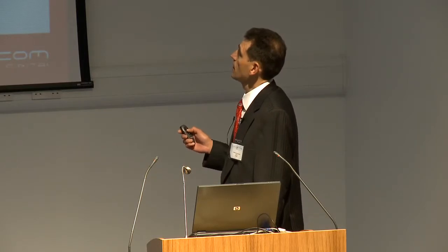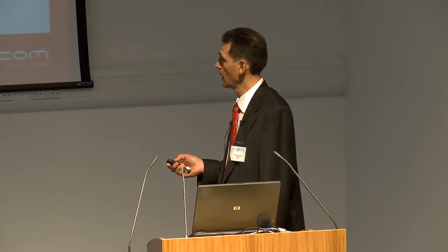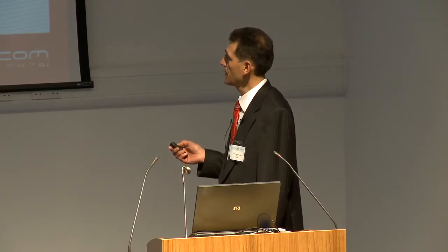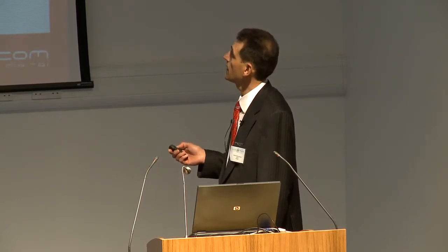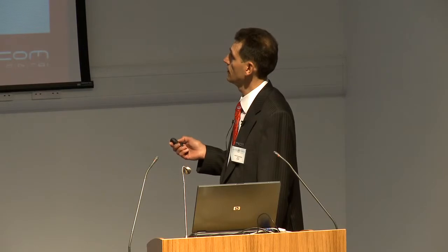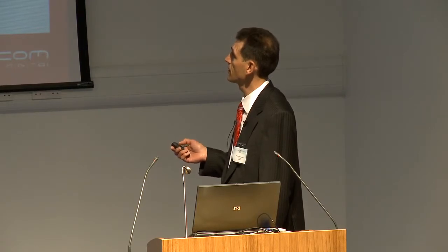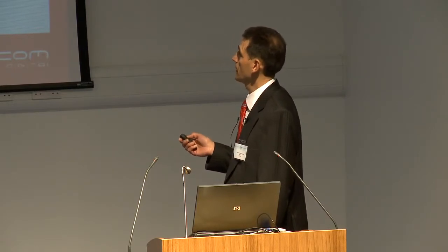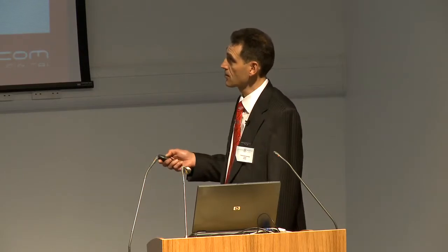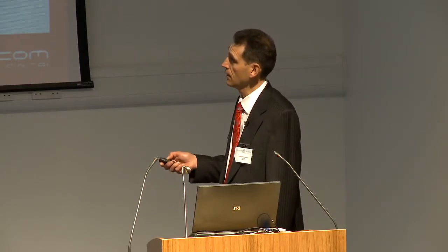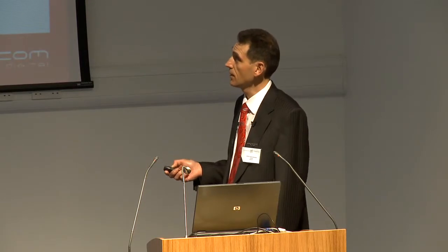So they were using also Camsonics and Trilithic leakage detectors at that frequency band of 2 meters. And what were the indications? Indications of Camsonics were 10 microvolt, 20 microvolt, and Trilithic were similar, while actually the leaking QAM signal was at 200 microvolt per meter and 400 microvolt per meter.